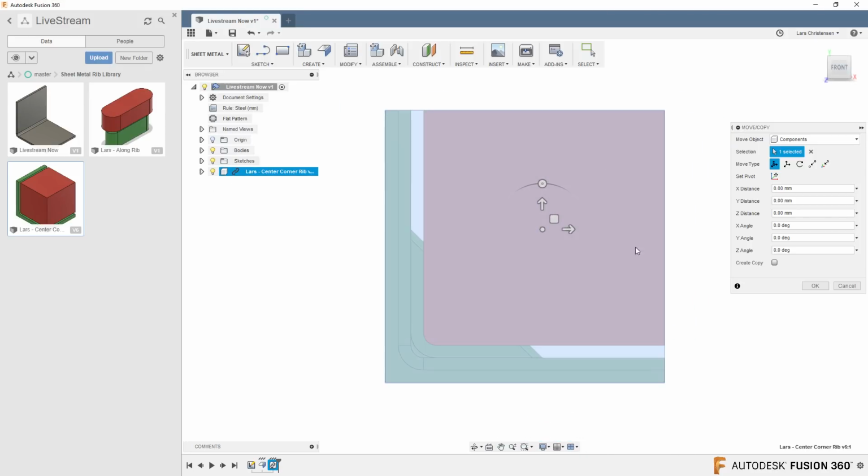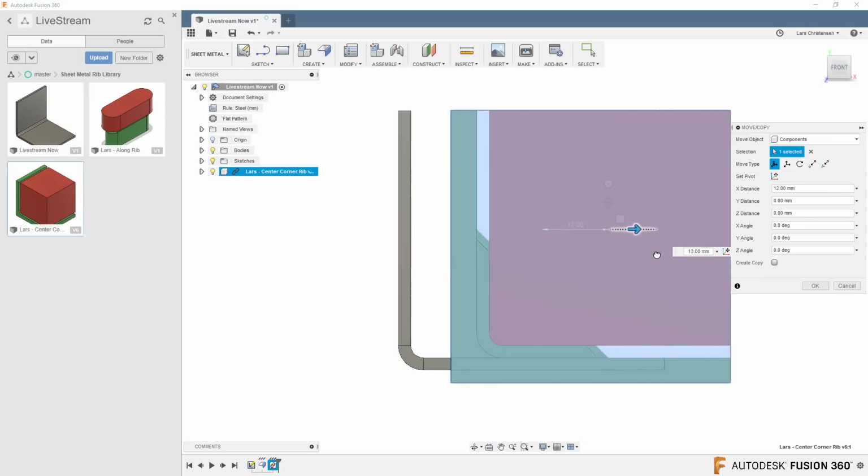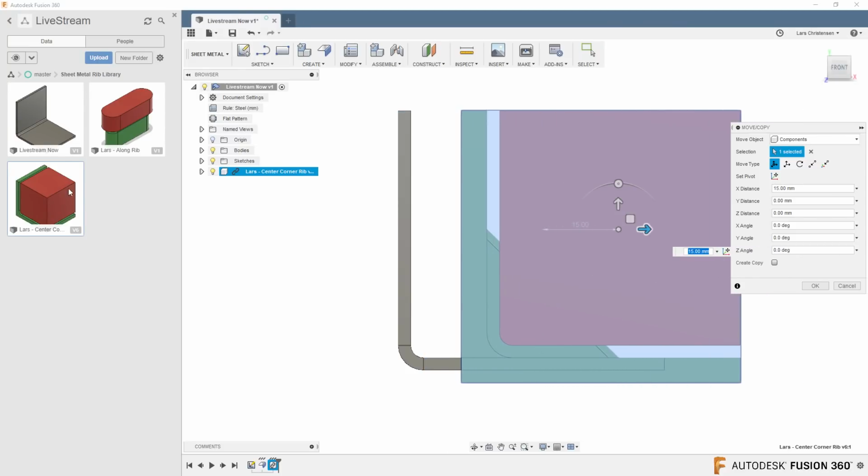And you might see, depending on how you model this up, that you maybe have to place this the right way. In this case, it's very important that this form tool has the right thickness compared to what your sheet metal does. Here I'm using, I think, 2.5 millimeter thick gauge steel. So I would have to create variations of these tools or the parameters depending on where I'm going to use them. That's maybe more advanced.